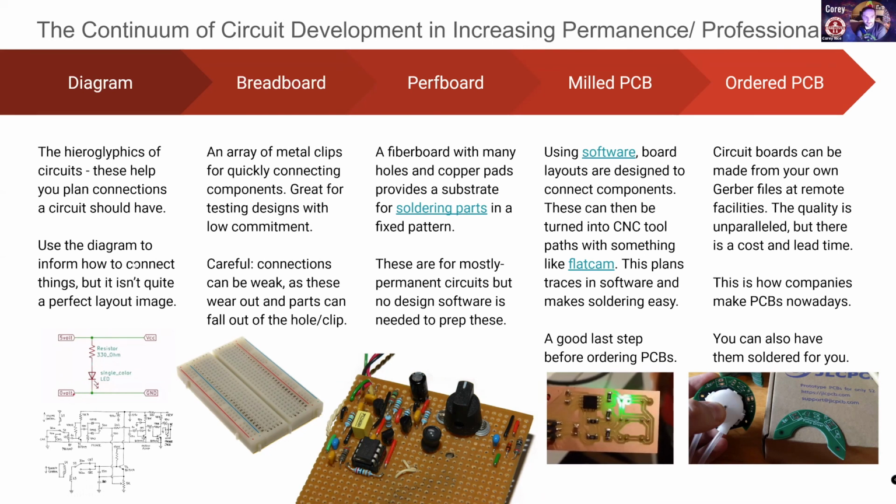If you have a diagram or an idea of a circuit, the next place that I usually build it on this progression is in a breadboard. A breadboard in my mind is the next step towards more permanent solutions, where you use a breadboard because they've got little clips inside that will grab onto wires or grab onto components, and you can easily pick them up and move them around. You don't have to solder anything. They're good for testing. They're low commitment, and they are to some extent expendable.